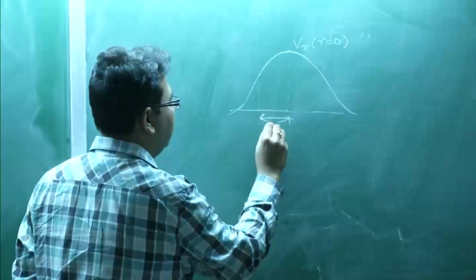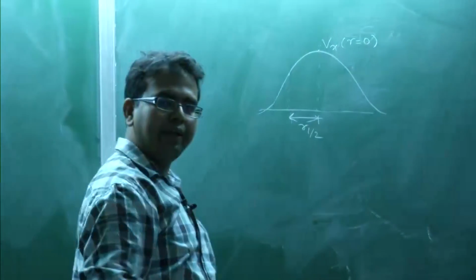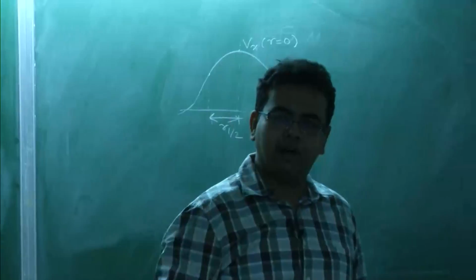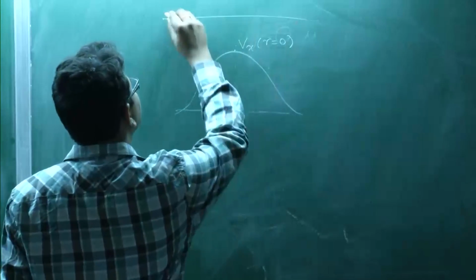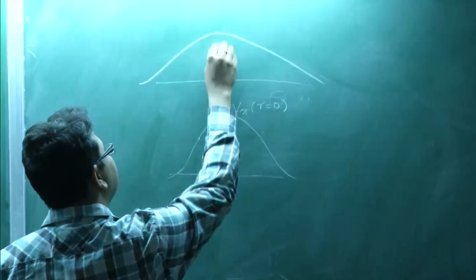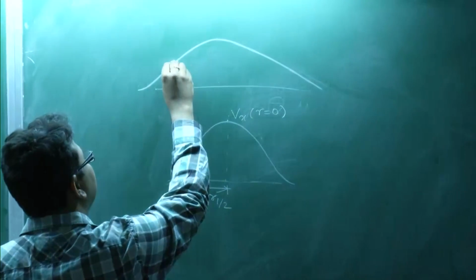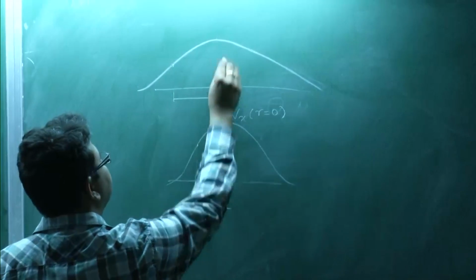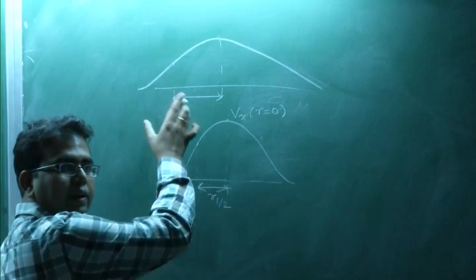And this radius is your half radius. So this gives us some idea about the jet spreading. If you plot the half radius further downstream, you will see that your jet is spreading. Your center line velocity will come down and it spreads more. So the jet is spreading.